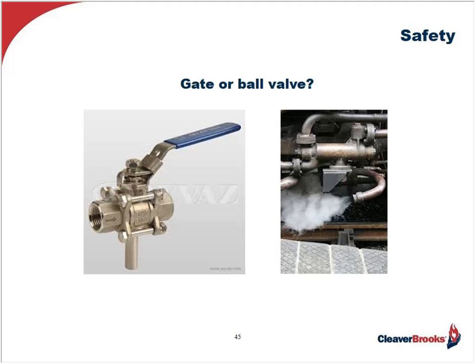Now, what we have encountered sometimes with some audits or assessments is the valve used for draining or purging is often a quick opening one-quarter turn ball valve with a handle similar to what's shown here. Now remember, this pocket is directly tied into the steam header, which is under high pressure. Let's say it's 100 pounds. That's 340 degrees. And if someone inadvertently catches a piece of clothing or bumps the handle on the valve, it could open sufficiently to seriously scald the individual and cause serious harm to him or her.